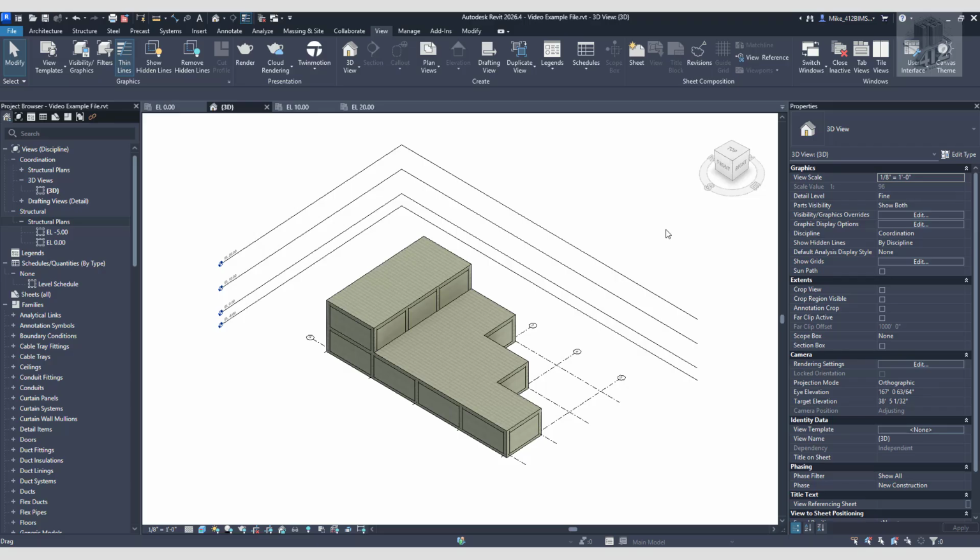These 3D extents act as a global default. Whatever you set in 3D becomes the baseline for all future views and remains consistent across the entire project. In contrast, 2D extents are view specific. You can adjust them independently in each view, giving you the flexibility to clean up graphics, control visibility, and tailor the documentation without affecting the model-wide extents.